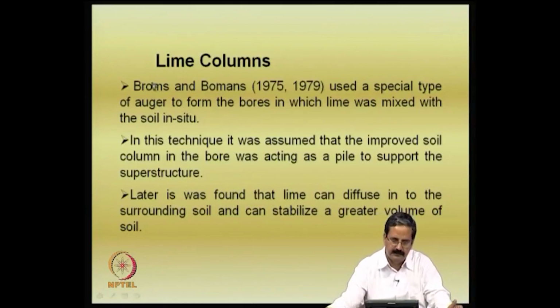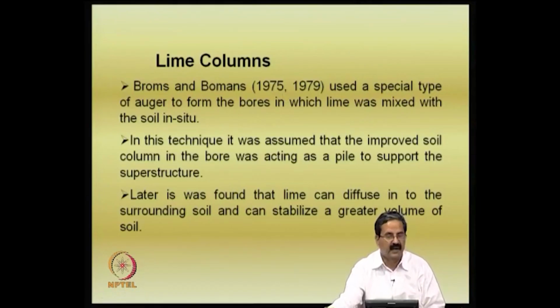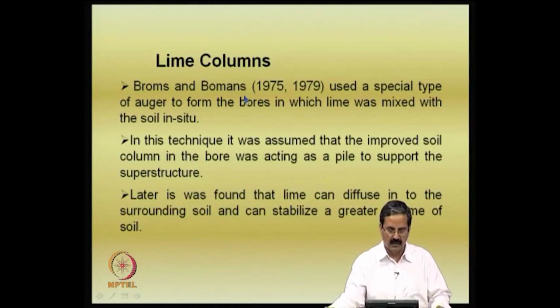In fact, Professor Brahms is from the Swedish Geotechnical Institute, SGI it is called. They did a lot of work on lime columns and lime stabilization. They have an ASCE paper on how to construct lime columns. In the case of roads, it is simple mixing, and we need to treat only the top half a meter to 1 meter.